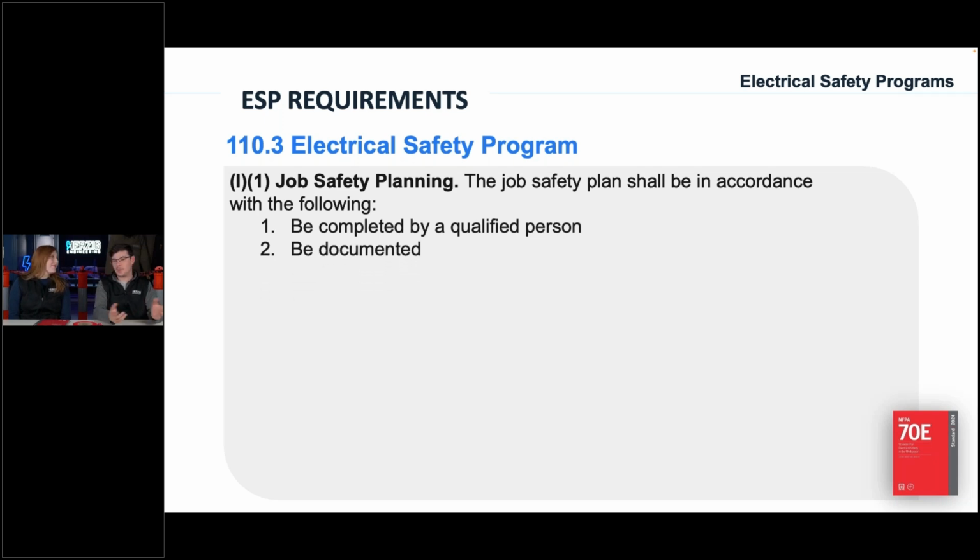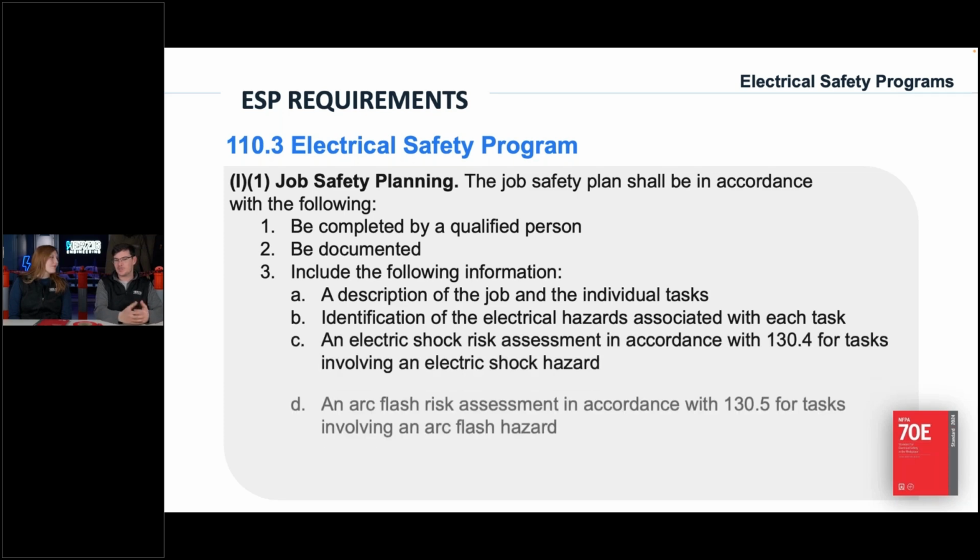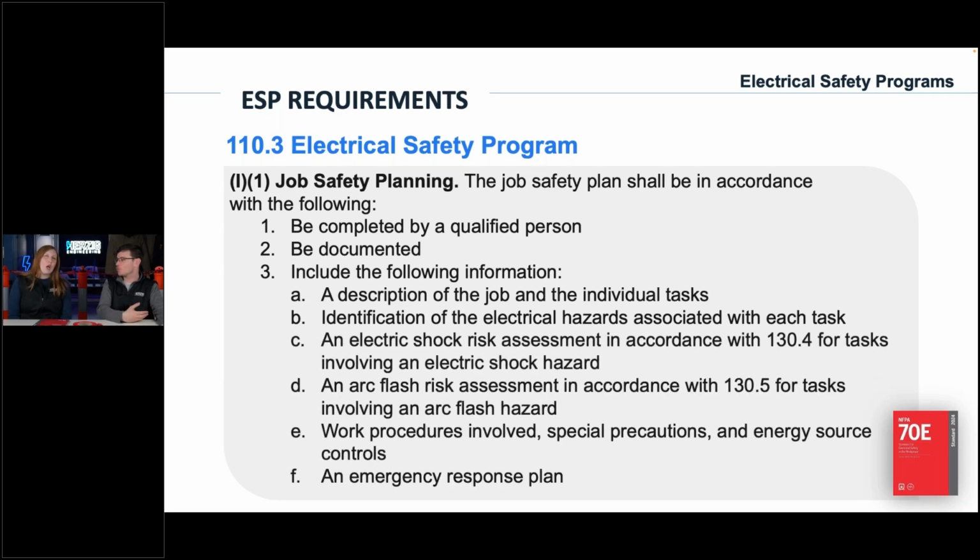So first, it must be completed by a qualified person. No unqualified person should be completing this because they're not going to be working on the electrical equipment, so they don't know the hazards they could be facing. It must obviously be documented. Document everything, write everything down. If it's not documented, it didn't happen, right? And include the following information.